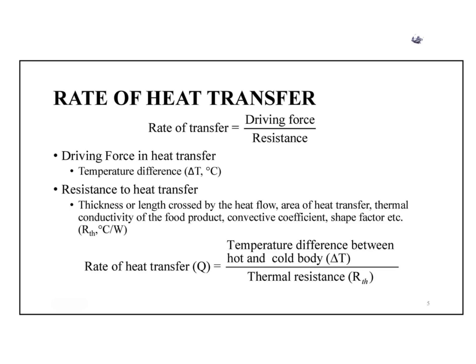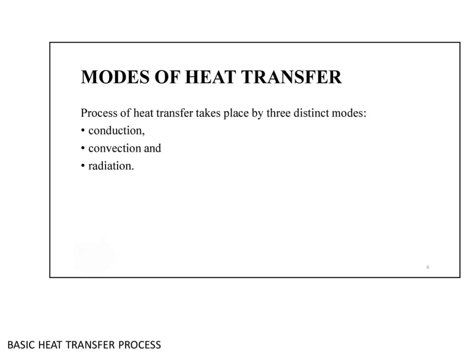Moving to next slide. Rate of heat transfer, driving force and resistance. The rate of heat transfer equals the driving force divided by resistance. The driving force is the temperature difference. Resistance includes factors like the thickness or length the heat travels through, area of heat transfer, thermal conductivity, convective coefficient, and shape factor.